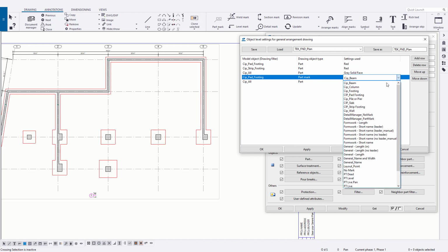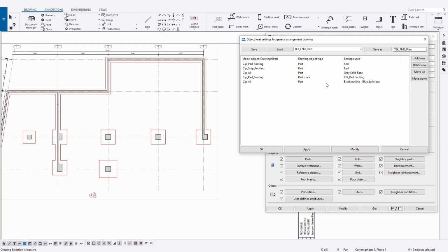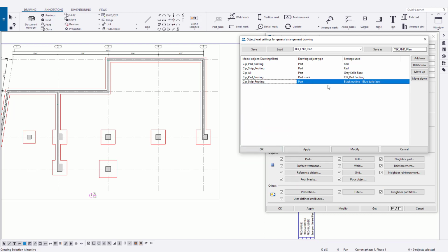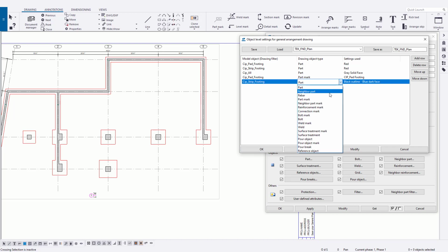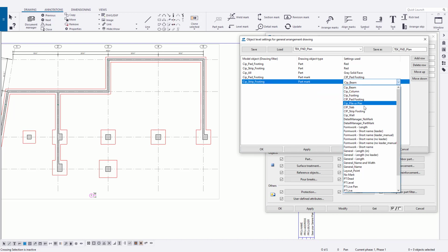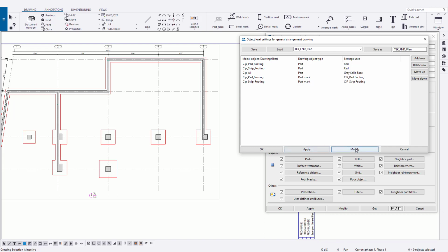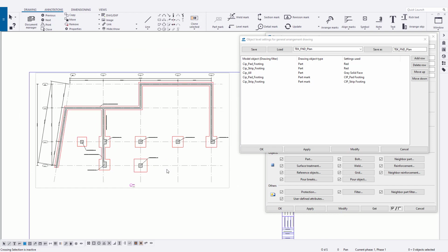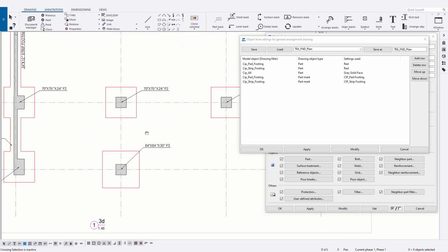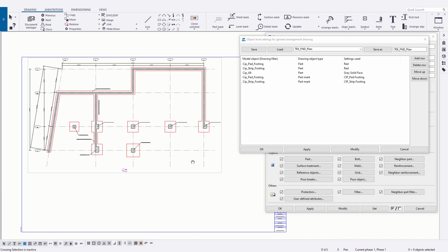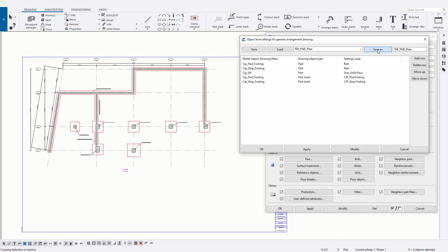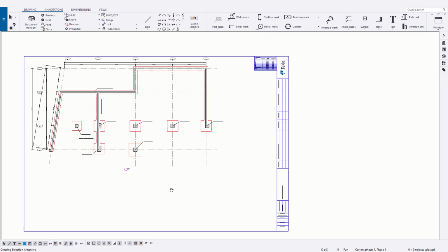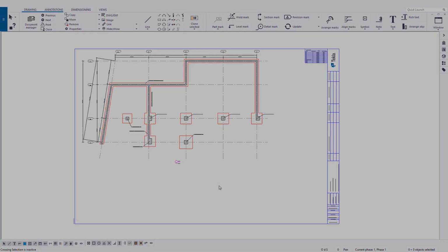As with most settings in Tekla, once you've finished, you can then copy the corresponding files to your firm folder for use in all future models. You may want to save all of your settings with a company abbreviation first, as it makes your custom settings much easier to find and manage. Creating object level settings can be an iterative process, so remain flexible to adjust your settings in the future. Once you've established your initial object level settings, utilize this as your starting point for additional object level settings that are more applicable to other drawing types or view types, such as sections and details.